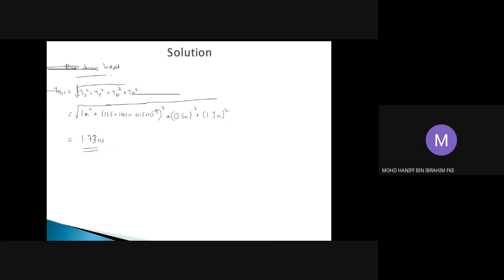From these, you can calculate what the rise time value should be. So we're going to have 0.7 divided by 400 megabits per second. That basically will give us the value of 1.75 nanoseconds. So this should be the maximum allowable rise time.